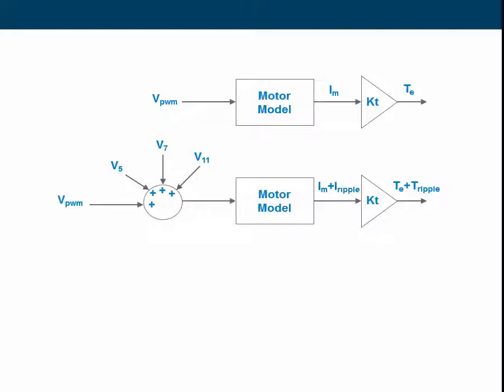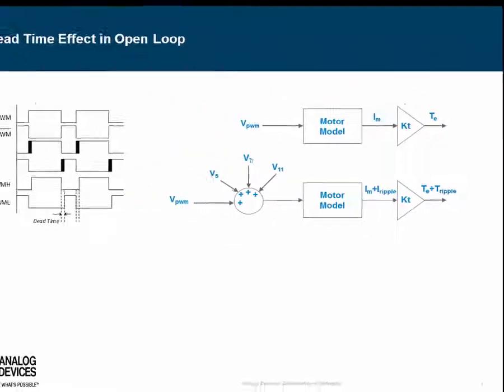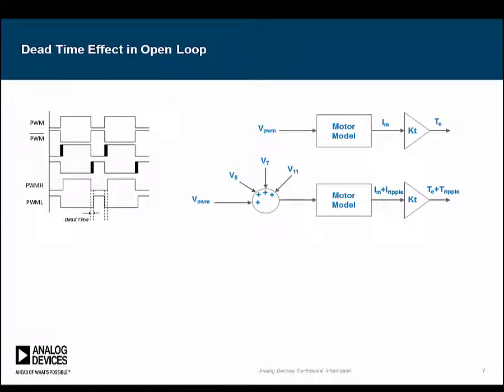Low-speed operation is important because it is in this mode that the applied motor voltages are very low, and the error voltage from dead time can be a significant fraction of the applied motor voltage. Moreover, at low speed, any induced torque ripple has a more detrimental impact, since the filtering effect of system inertia at higher speeds is not available.